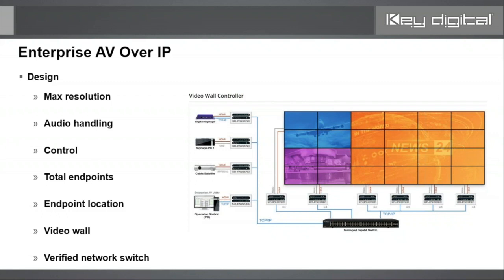You need to know what is your desired maximum resolution. How do you wish to handle your audio? Why? Because when you go over a network, you will encounter latency. We'll talk more about that. How do you wish to control the system? We give you a number of available options at Key Digital. How many total endpoints will there be? That's encoders plus decoders. And where will they be located?